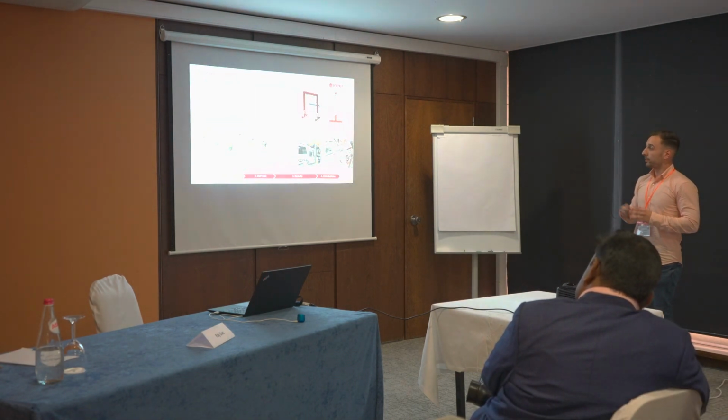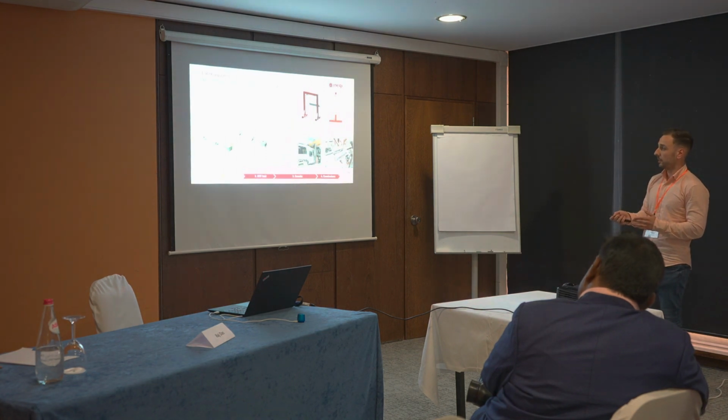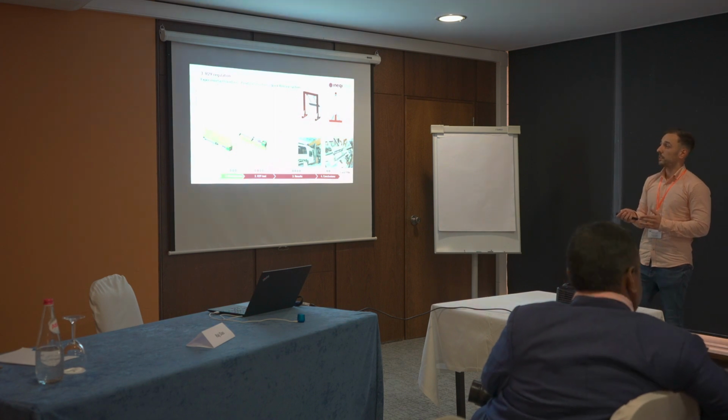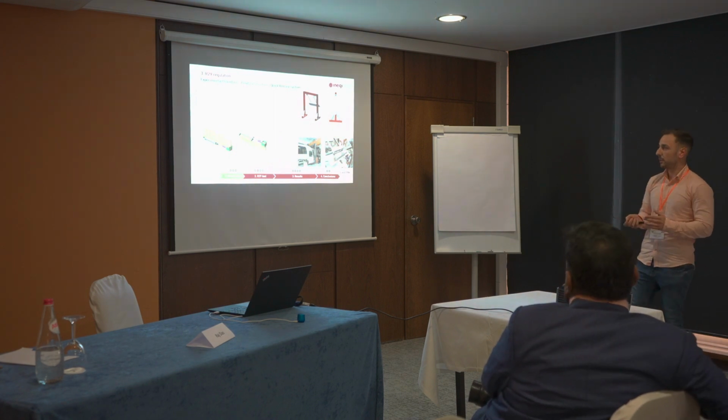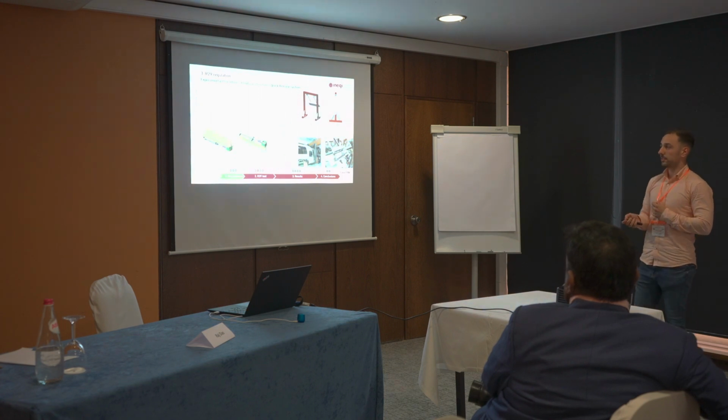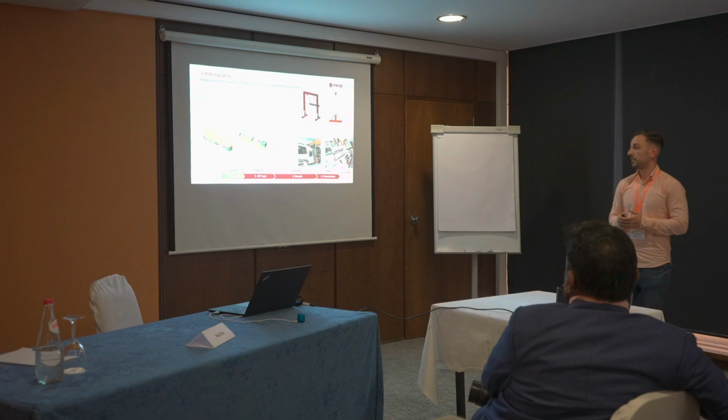And so, to perform the test, it is necessary to develop a striker, an impactor, and our impactor weighs 2,500 kilos and will transfer to the section more or less 55 kilojoules of energy.